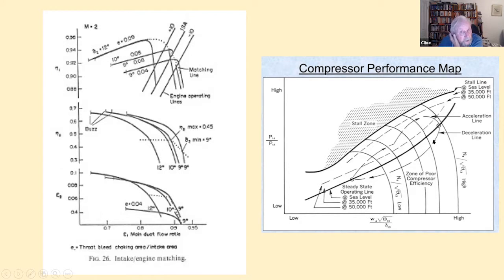Except that if the engine behavior should shift, and sometimes it does, if it moves towards a higher pressure ratio, so mostly in that direction towards a high RPM, then it's obviously going to demand more flow, so it will actually try to move in that direction, and vice versa if it comes down that way.